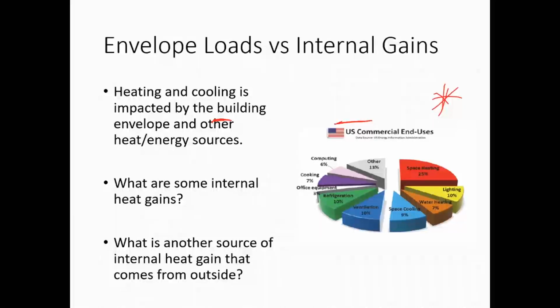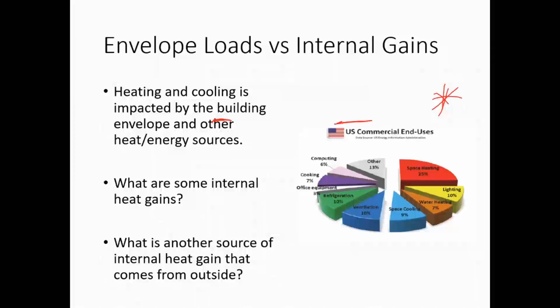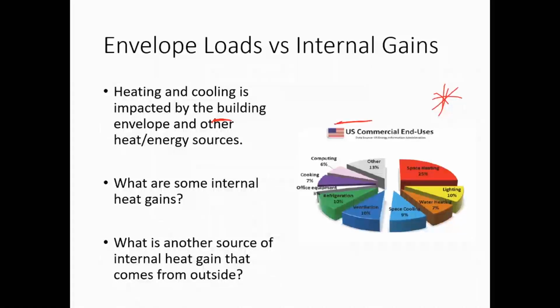So these are all things that are tied together, that are going to increase our heat gain, and affect the condition inside of our building. When we pay attention to how we specify our construction assemblies, we can have operable blinds and stuff like that to keep sunlight out, and that hot afternoon sun in the summers, and have appropriately sized overhangs on our building.